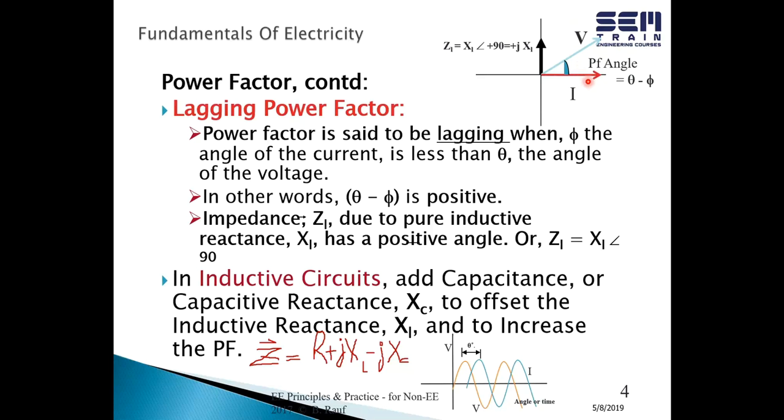So anyway, let's just imagine a situation. You've got a lot of inductive reactance in a system, in a building, in a facility, and that is causing the current to lag behind the voltage by 30 degrees. So the power factor currently is 0.866 or 86.6%. And your charter is to correct that power factor to 100%, unity, the utopian power factor value. Although in real life you rarely attempt to go after a 1.0 power factor, you improve it to a reasonable level. There are economics involved, engineering economics, energy economics, but we're not going to get into all of that now. So bottom line, the current is 30 degrees behind the voltage, and therefore the power factor is 86.6%. Your objective is to improve the power factor to 1.0 or 100%.